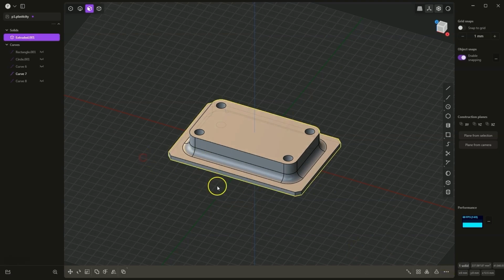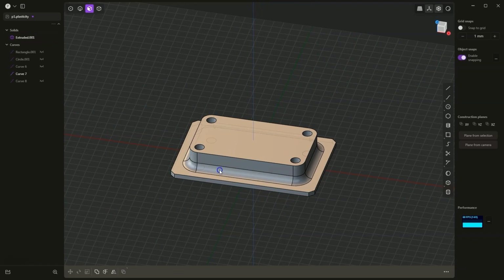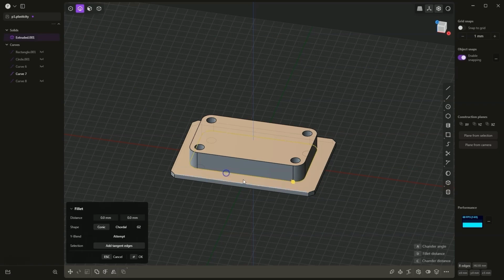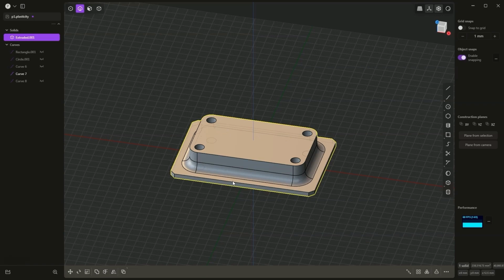And if you want to set a specific radius value, after clicking on the radius, information about the dimension of this radius appears here. It is 7 millimeters, and just by dragging it in one direction or the other, we can adjust it. We can also select the entire radius. Then we can press the X key on the keyboard, and this will remove the radius. Now I switch to edge selection. Again, with the Alt key, I click on this line to select the entire chain. Here, for example, I type D8, enter, enter again, and I have added a specific radius value of 8 millimeters.